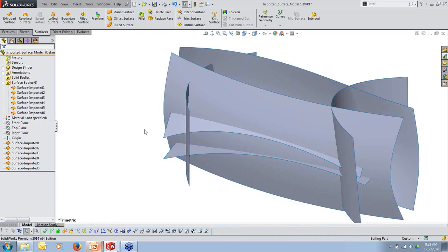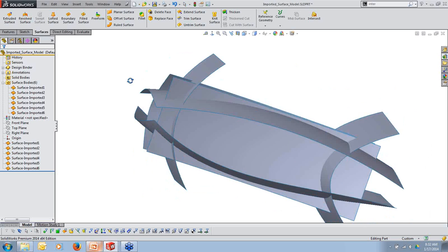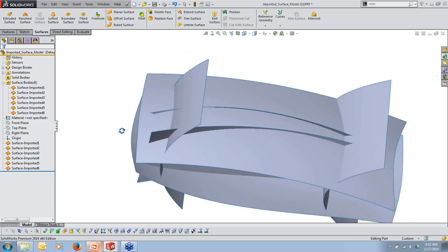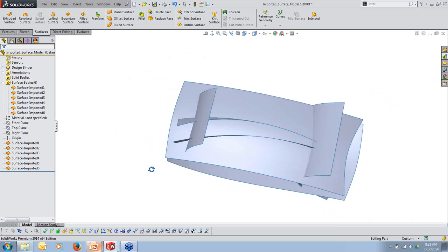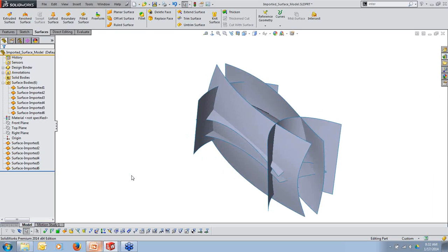So Franco mentioned my surfacing part that we were working on. And what we have here is just a handful of different surfaces, and these surfaces are all just kind of intersecting each other. This is fairly typical when you're setting something up in SolidWorks using surfacing to try to get some complex shape. Now it's a lot easier to break it down into what shape each side takes on in order to generate each face independently.